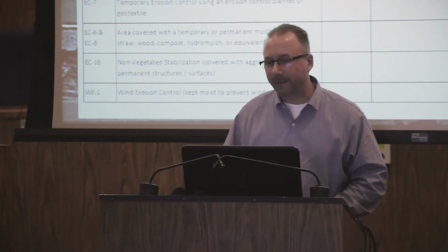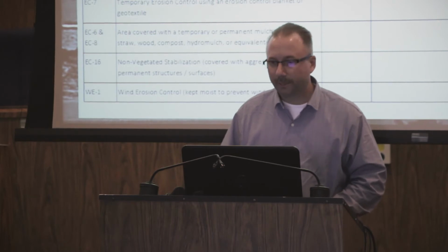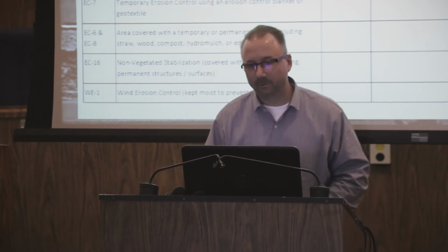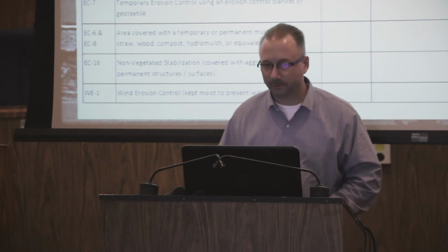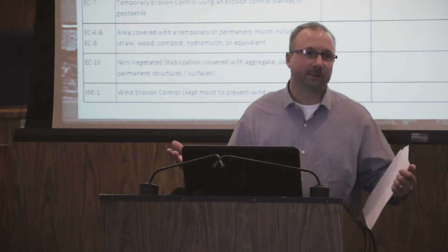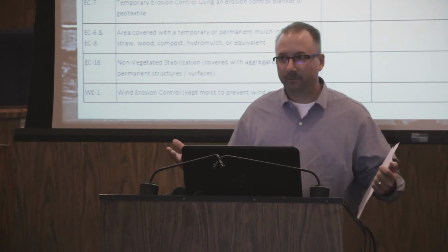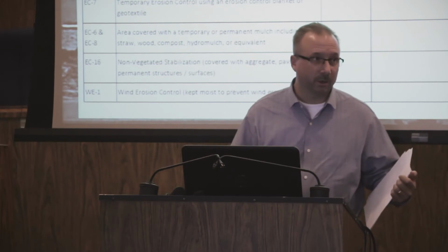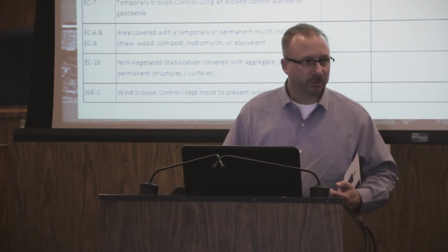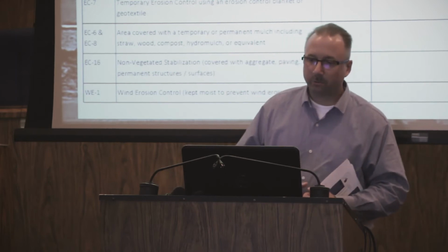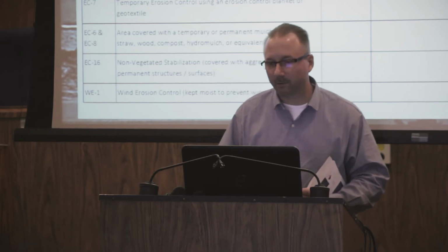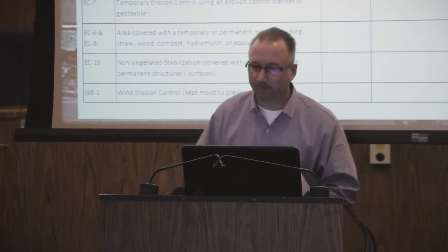Although construction by nature disturbs soil, it is vital to place a temporary or permanent covering over disturbed soil as soon as possible. So we're recognizing that you're going to disturb it, otherwise it wouldn't be construction. We're going to face the reality of the situation: soils will be disturbed. But as soon as possible, we want to put some sort of blanket over that to keep soils from becoming further disturbed by rain, wind, or further construction activity.